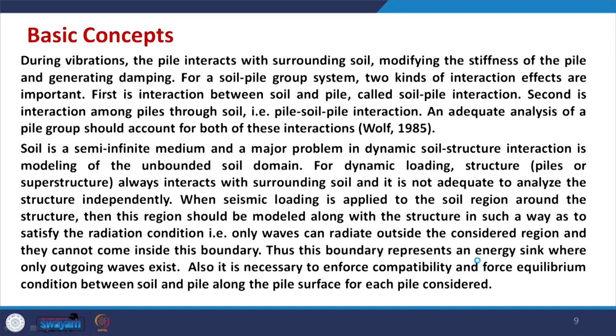What is the basic concept? Here the concept is that during vibrations the pile is going to interact with the surrounding soil. So the pile is not alone; that is the basic difference between a column and a pile. When we talk about a column, it is a simple structure, and we do not talk about soil. But when talking about a pile foundation, we need to consider the surrounding soil also, and as a result this surrounding soil will modify the stiffness of the pile and generate damping. So what we are going to talk about is ultimately the stiffness and damping properties of the whole soil-pile system. We are not going to consider only the pile or only the soil; it will be together.